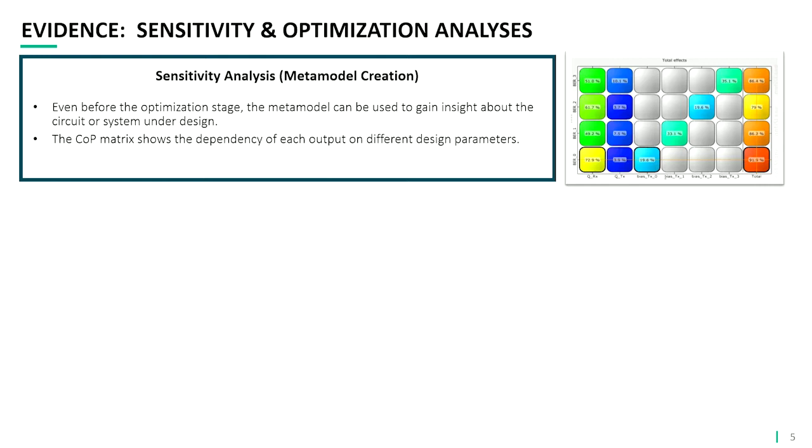It gives you the relationship between all the outputs as a function of the input design parameters, which are on the x-axis. And if you look at the plot, you'll see right away that the Q factor for the receiver rings plays a major role in determining the bit error rate, whereas the next column, the blue one, is the Q factor of the transmitting rings, which doesn't have almost any effect. You can also see that the bias of the 4 rings in the transmitter plays some role in dictating the bit error rate. So this type of insight is developed over years of experience running simulations, doing tape-outs. It's really nice that you can launch these simulations from optiSLang into INTERCONNECT and get these insights very easily.